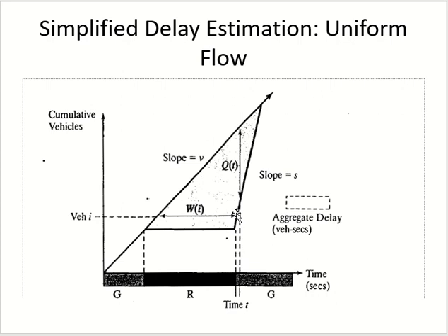So you take the difference. That is the waiting time, which is the time in queue delay. The vehicle came, it joined the queue, and then it left. So waiting time is the time in queue delay, the fourth one. Got it? So if you take the difference on the y-axis, you get how many vehicles are in the queue. If you take the difference on the x-axis, you know how much time the vehicle was in the queue. Clear?